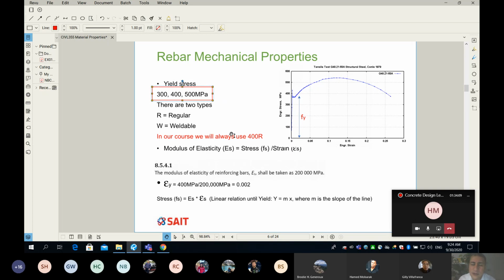Okay, guys, some of you think that every metal is weldable. Some rebar is not weldable. It means you cannot weld it with welding sticks. But some are. Typically, in most cases, 99%, we do not weld the rebar together. And remember this, we do not weld the rebar together. Yes, because assembly welding is super expensive. I guess the welder hour is above $100. And a fresh engineer is only $30 something. Very, very expensive to weld the rebar.